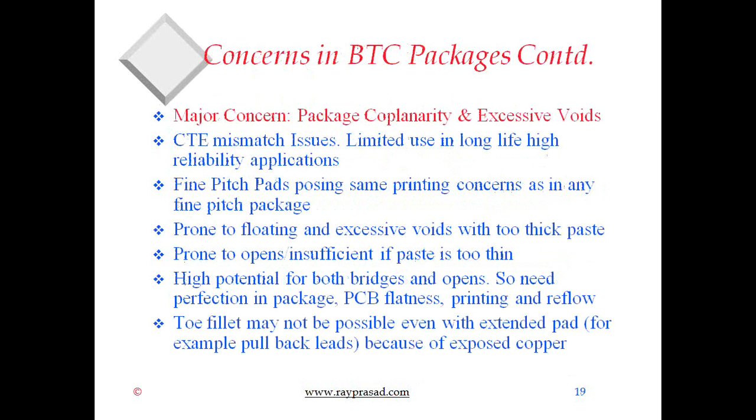Now, it's not without a price. Nothing is cheap, however it may appear. The purchasing guy might be happy, but when it comes to manufacturing folks like us here, the people dealing with design and manufacturing, they are going to have to face all the challenges. The concern basically is package coplanarity. You don't have a lead coplanarity issue because the whole thing is flat, but the package itself, after all, is a plastic package, and depending on how it's made, it may not be flat.